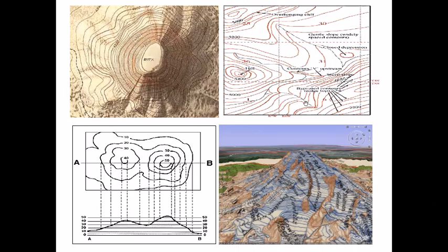If you see this diagram over here, it's covering more area. You can see that again we have these complete loops, and the centermost loop has the highest elevation, and as you go down from there or away from there, the values on the contour map decrease. That means the elevation is most at the center, and the circumference is lesser, and as you go down, it keeps on increasing. So this tells you a picture that this is part of a hill.